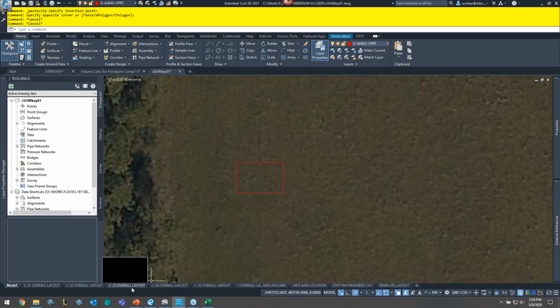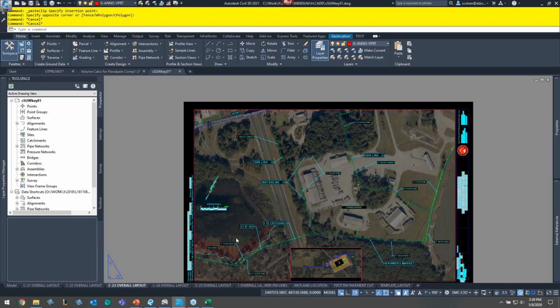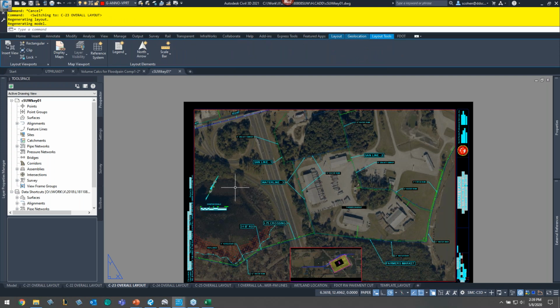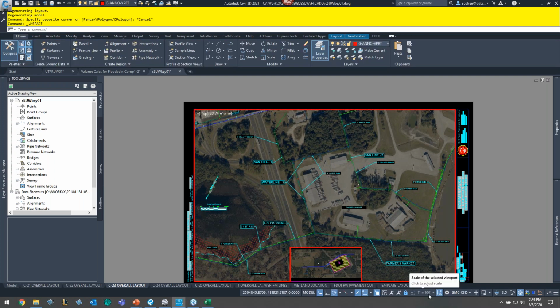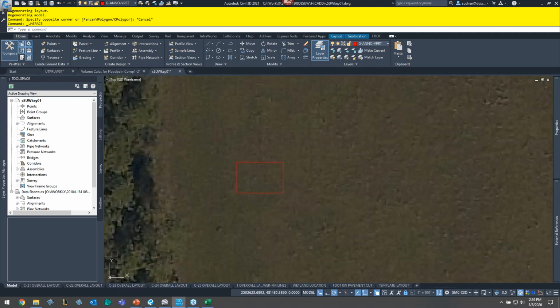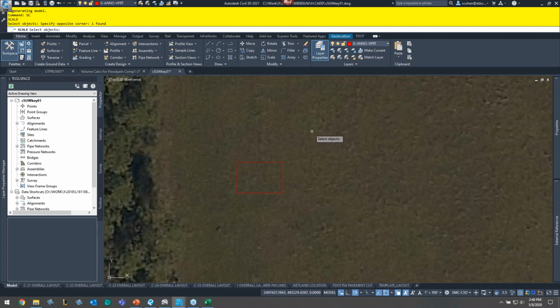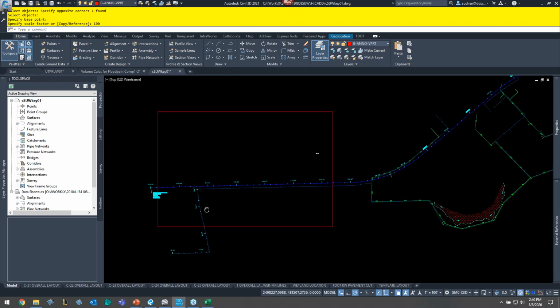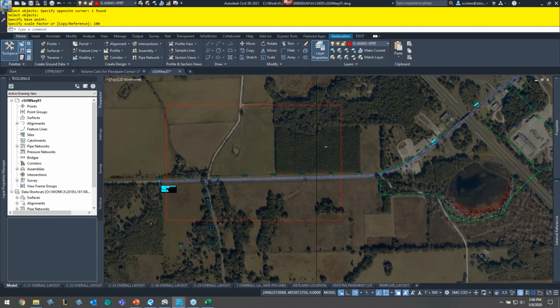What scale am I plotting at? Well, in general, I kind of figured that out. Let me just double click inside one. I want to plot at a 1 inch equals 100-foot scale. So I'm going to scale this rectangle, this polyline, by, yes, you should say 100, just 100. So that gets me the size that I need to cover for these sheets of paper.